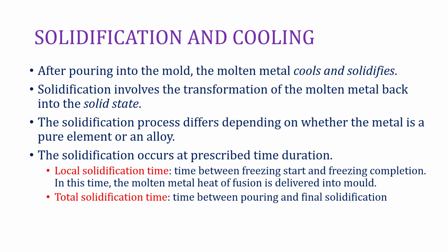Now we shall move on to the next important topic in casting, which is solidification and cooling, because this defines the entire structure of a casting. As soon as the molten metal enters the mold, it starts transferring heat to the surrounding sand. Gradually the temperature decreases until the liquid transforms into a solid. The manner in which solidification occurs depends on whether the material is a pure metal or an alloy.